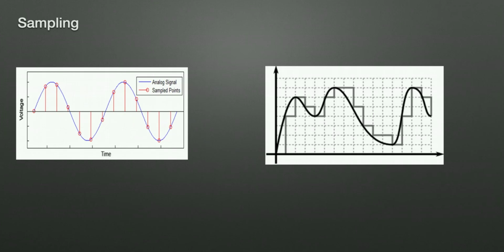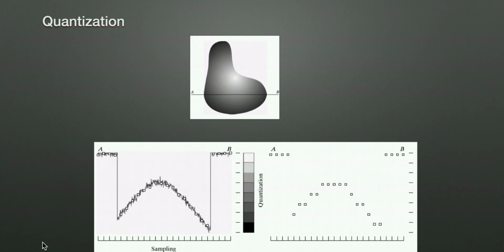So the main difference between sampling and quantization is explained in this slide. So I'll be very clear. Sampling is basically taking it from the input form of things, choosing which points you want in this range. That's your time or whatever that may be. So in this particular range, that's your horizontal axis, whatever values you get, let's say you want to take it from the second point or the third point or the fourth point or the fifth point, those are known as sampling. Quantization is through the amplitude. All right, so sampling is through the time frame or the horizontal axis, and quantization is the amplitude.